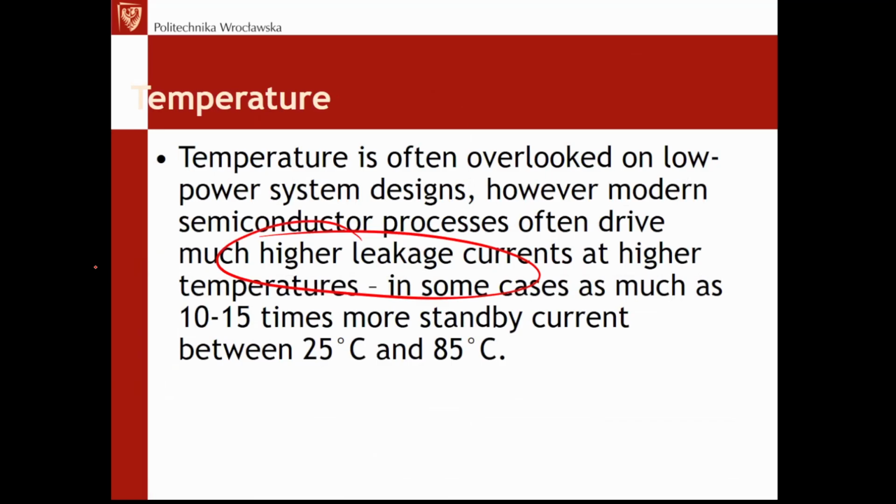Here the leakage current is rising dramatically, I would say. So of course we start from nanoamps, sometimes hundreds of nanoamps. So even if it rises 10 or 15 times, we are still within microamps, sometimes even a bit below.